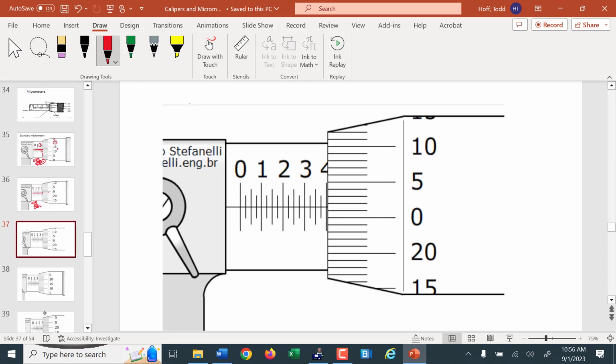I'll give you a minute to read this one on your own. What are you getting? 0.401, 402, either one I would accept. That one's almost exactly right in the middle, isn't it? 4015. There's a good point. Can we say 4015 since it's right in the middle? No. If we say that, then you're implying that your measuring device went to the 10,000th of an inch, and it doesn't. So it's really tempting to fill those in, but we can't do it.